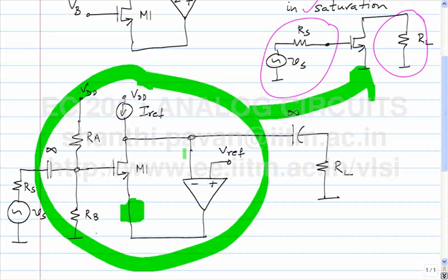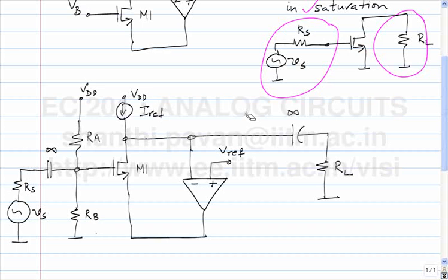It is some large number multiplied by the incremental voltage at the drain. Okay, that's something that you certainly don't want. So, any suggestions on how I might be able to avoid this? Okay, so one suggestion is, for incremental signals, you want this node to be connected to ground. So, put an infinite capacitor here.